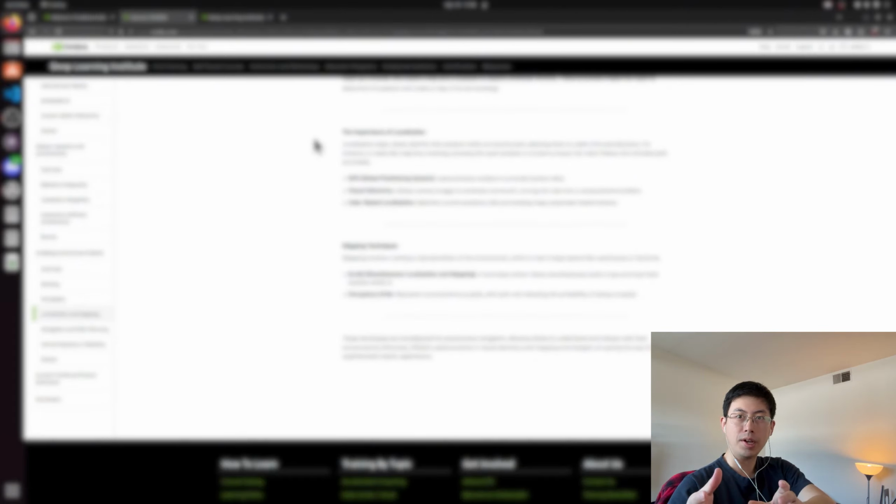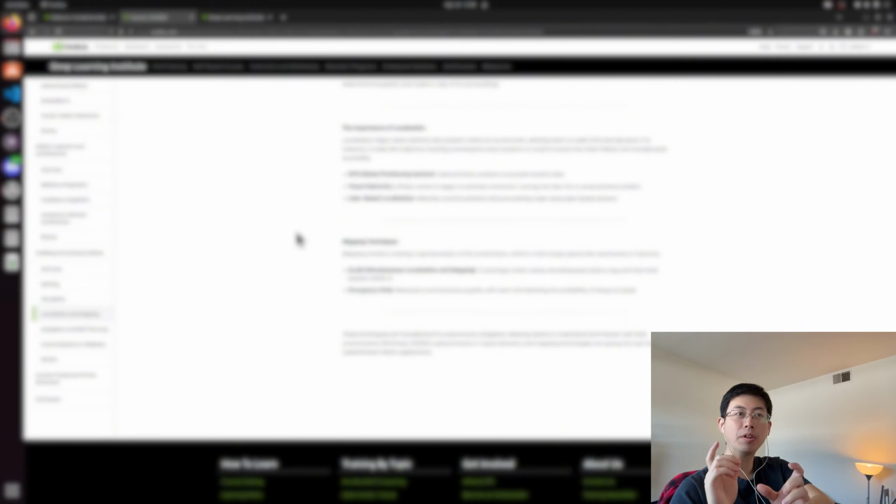In terms of visual odometry, you use a camera to understand where you are, what we call the pose of the camera. You can also use LiDAR to do the same thing, but the algorithm is a little bit different. Usually with LiDAR, you use something called ICP, iterative closest point, to understand how your LiDAR has moved. For LiDAR, it's called LiDAR odometry. The mapping technique goes hand in hand with your localization or odometry. This is often described as a chicken-or-the-egg problem: how do you estimate yourself in an environment if you don't know that environment? So at the same time you have to try to map the environment.